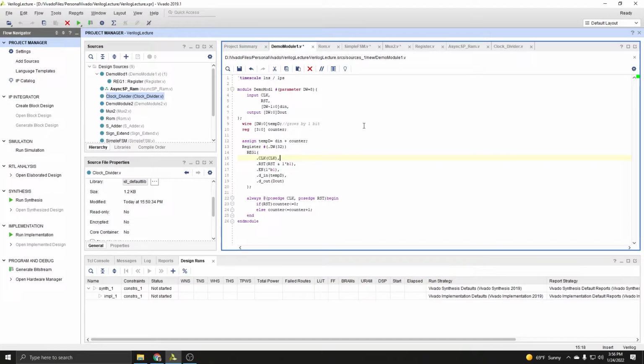So what this allows you to do is, let's say you have a register, in this case, this register. You don't need the enable signal, but you don't want to have to write Verilog for 2 different registers. You don't want to have a register without enable and a register with enable.